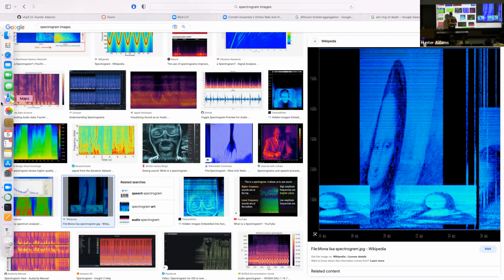You could do sound localization projects. Compared to the speed of the RP2040, sound is pretty slow. So if you had a collection of microphones communicating to the analog to digital converter on the RP2040, you could measure the delay associated with a sound hitting this microphone versus this microphone and deduce the direction from which the sound came.